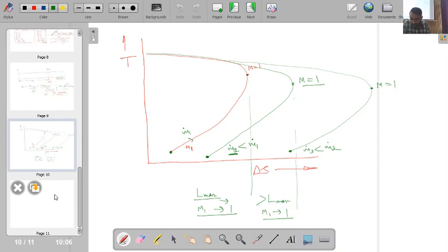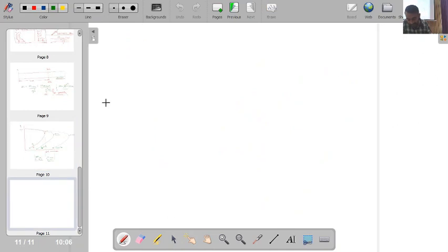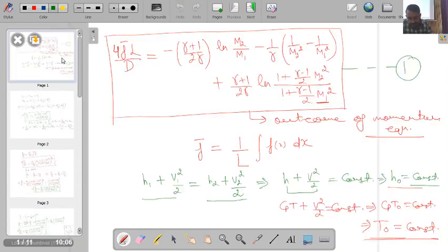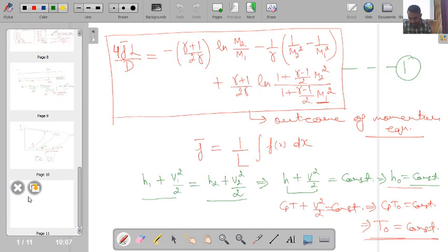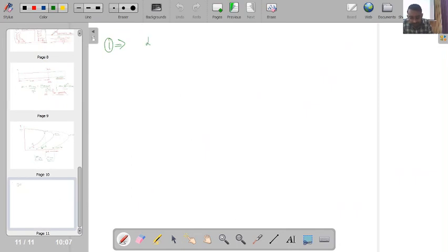Okay, so next point, now let me go back to my equation number 1 again. From equation number 1, if our L is the length, then we were able to get some Mach number M2. However, it is very clear to us now that we have some Lmax value here, corresponding to which for a given mass flow rate, my M2 Mach number is nothing but 1. So let's try to see for Lmax how this equation behaves.